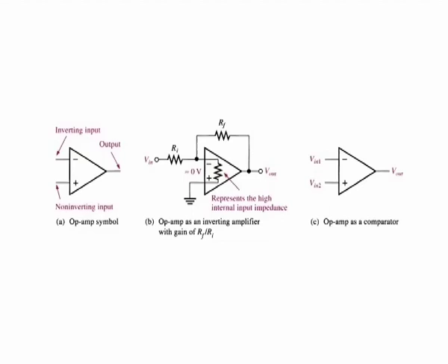The two important ADC parameters are resolution, which is the number of bits, and throughput, which is the sampling rate an ADC can handle in units of samples per second. Before getting into ADCs, let's look briefly at the element that is common to most types of ADCs and DACs. This element is the operational amplifier, or op-amp for short.